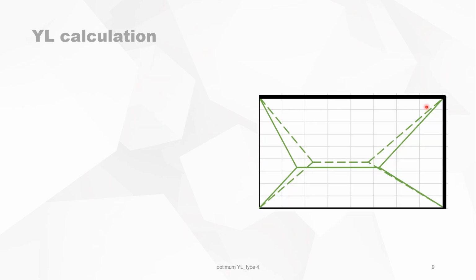Now let's look at the rectangular slab where B is 8.1 meters, A is 4.5 meters, and it's loaded with 20 kilonewton per square meter. The full green lines is the 30, 45, 60 rule. So it means this is 60 degrees, this is 60 degrees, this here is 30 degrees, and this is 45 degrees. We know that for having a realistic yield line pattern, we must comply with this equation.